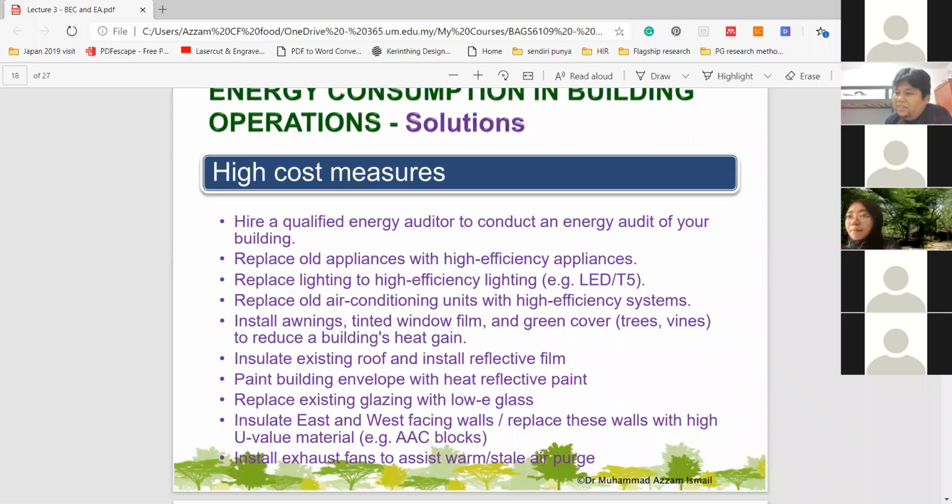But nevertheless, an old central aircon system might not be good for your health actually. If you have not been looking after the ducting, especially, there might be a lot of pathogens in there, a lot of dust, a lot of really dirty bits in there as well. So you're breathing really bad air technically, right? So you might get some animal droppings in it as well. So if you can, flush out the system regularly. After a few years, you flush it out again.